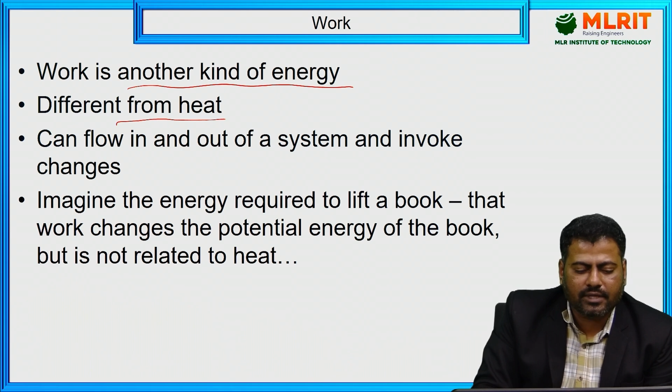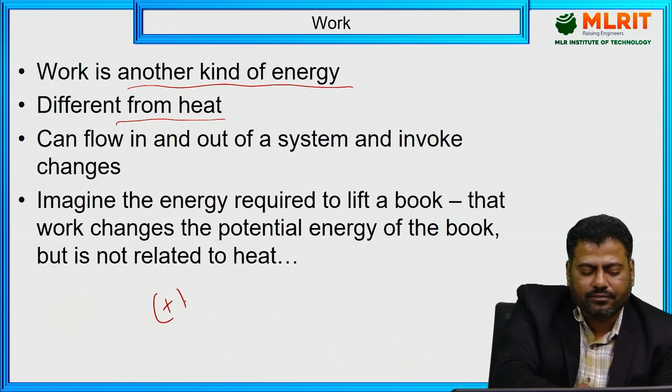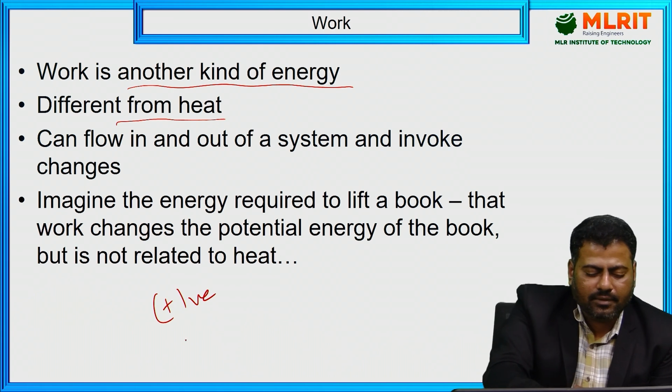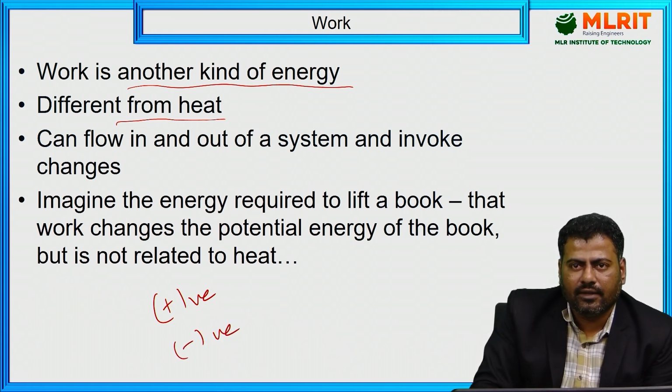And with respect to the mechanical work done, it is positive if I am extracting work from the system, right? That is the ultimate aim of the heat engine. For engines, we supply heat energy and that is converted into mechanical work done. So that is what we call desirable. Whenever we get work output from the system, that is always positive. If I am supplying work input to the system, we call it negative, like compressors and pumps. For that we have to supply work input to the system.